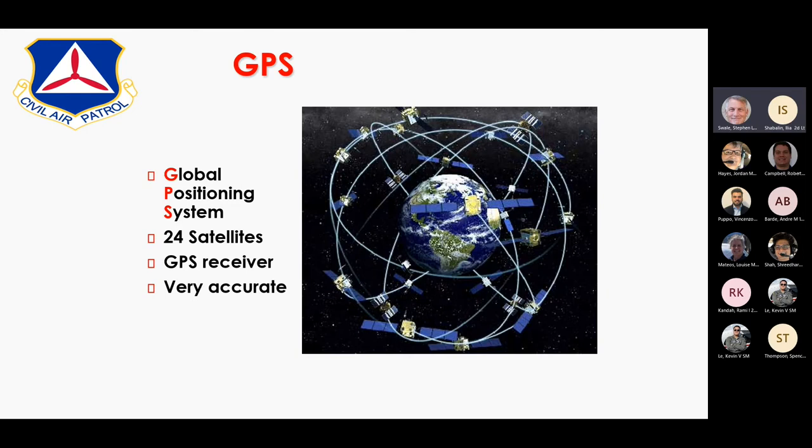I would recommend that whenever you're thinking about a mission, you minimize the number of waypoints to the absolute minimum, and that you make sure you don't skip the step of validating what you've entered by looking at the map, in the case of G1000 in the MPD, to see that it does make sense and that it does seem to agree with the sectional that's presented underneath it.